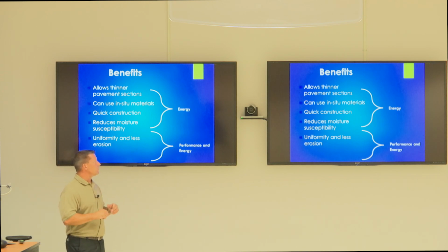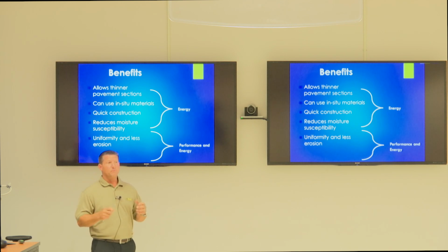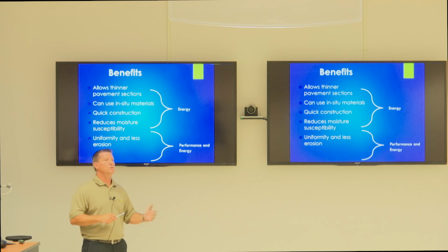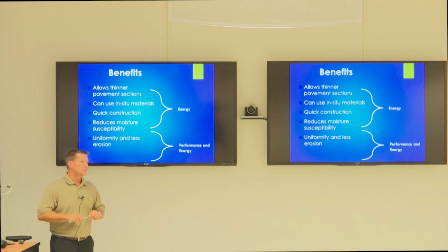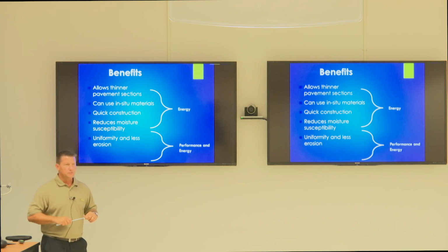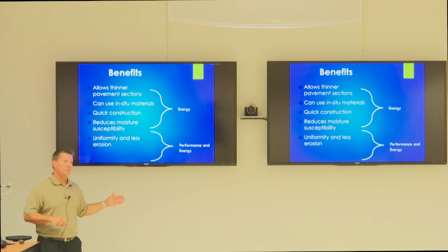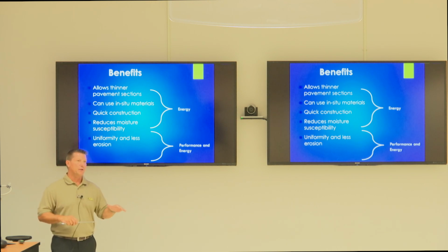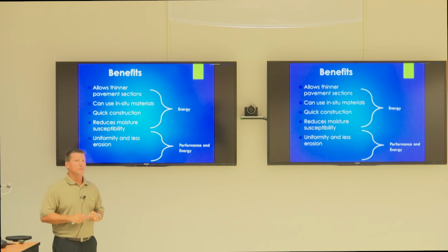Uniform distresses and erosion: you're limiting that, and they go hand in hand. We've seen some issues where a hurricane will go through the beach, where we can limit that erosion. Certain sections of the roadway down in the Outer Banks, Route 12, have been reclaimed, and the water washes off the asphalt and strips it off of the reclaimed material, and the reclaimed road is still sitting there because the currents were so strong. So it does really limit that erosion issue.